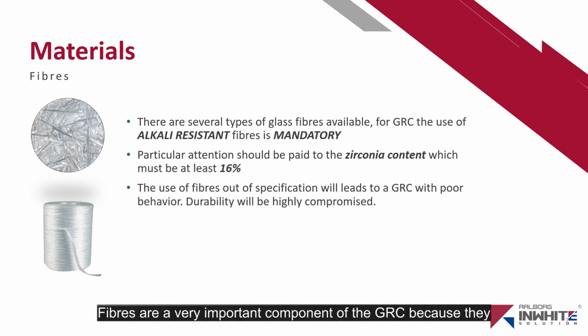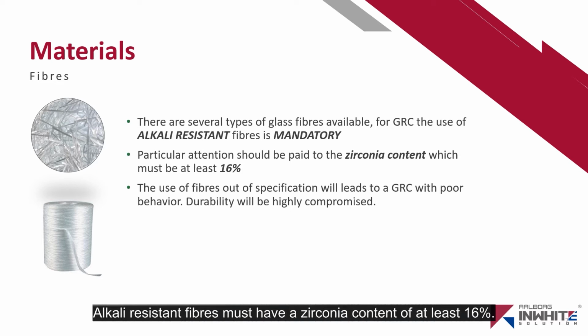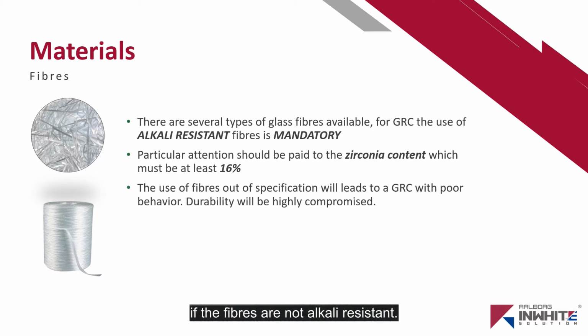Fibers are a very important component of the GRC because they allow us to fulfill the flexural properties needed. The use of alkali-resistant fibers is mandatory, otherwise the high alkalinity of the cementitious system will destroy the fibers in hours. Alkali-resistant fibers must have a zirconia content of at least 16%. Durability of GRC will be very compromised if the fibers are not alkali-resistant.